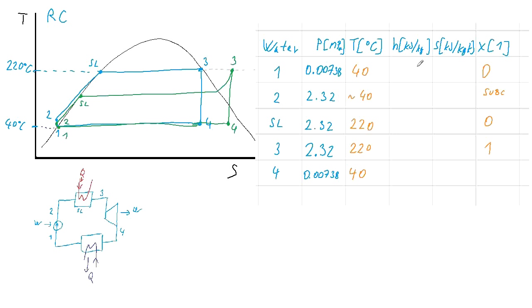Now, for some of these points we can also get the values of enthalpy. So the easiest with the diagram would be the enthalpy at the point 3, because it's the area which is shown on the diagram, the intersection of the vapor line and of the isotherm or isobar, and we will get the value of enthalpy being 2800.95 kilojoules per kilogram.